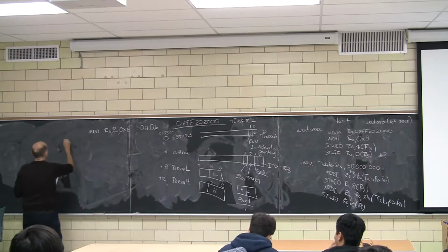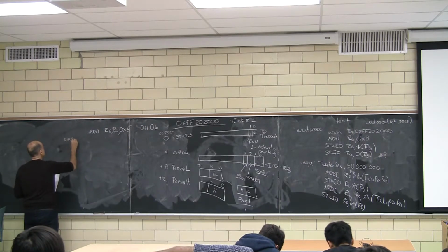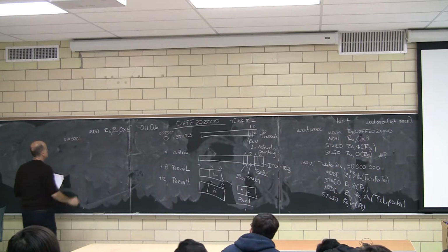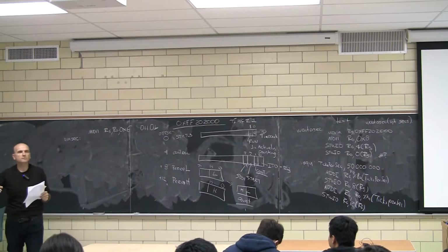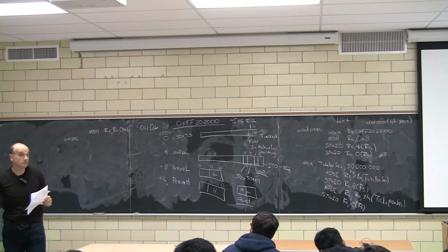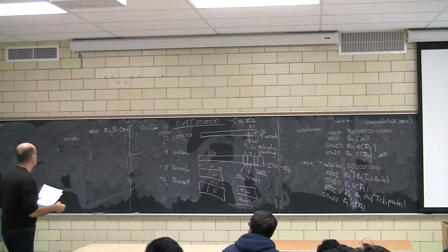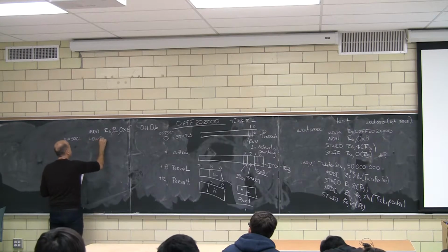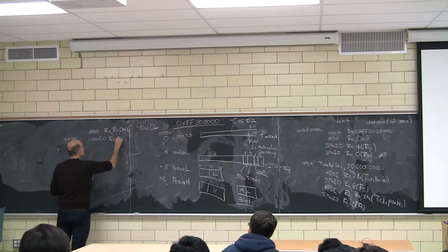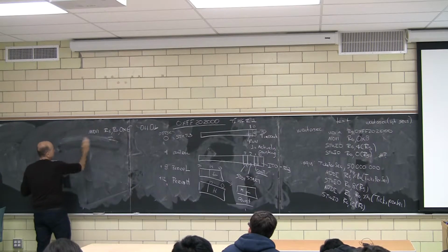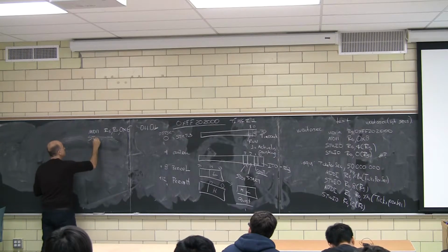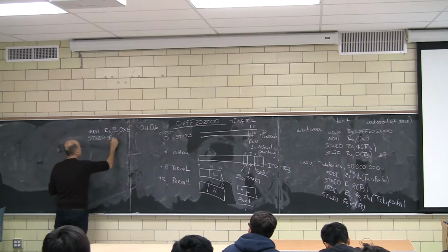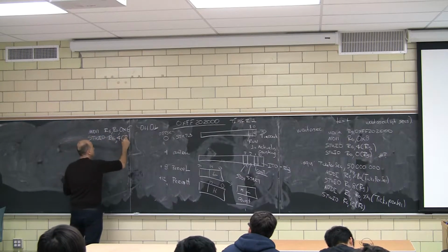Then let's go and wait for 1 second. What we're going to be doing now is we're going to keep asking the timer, did you time out? Did you count 1 second? So we're going to be doing a load word IO R6. Oh, maybe I should actually write it somewhere. Store word IO R6 4 R5.